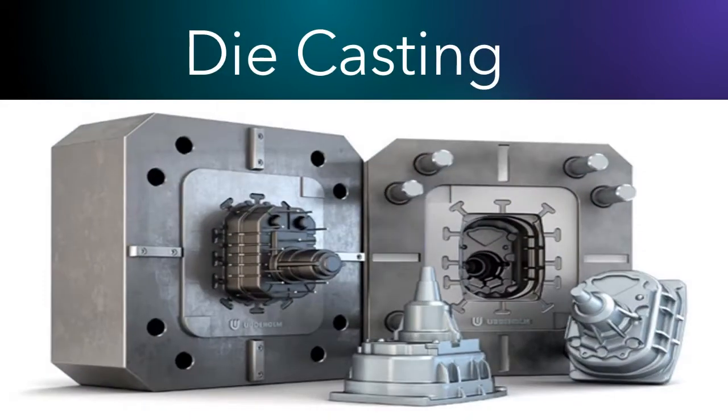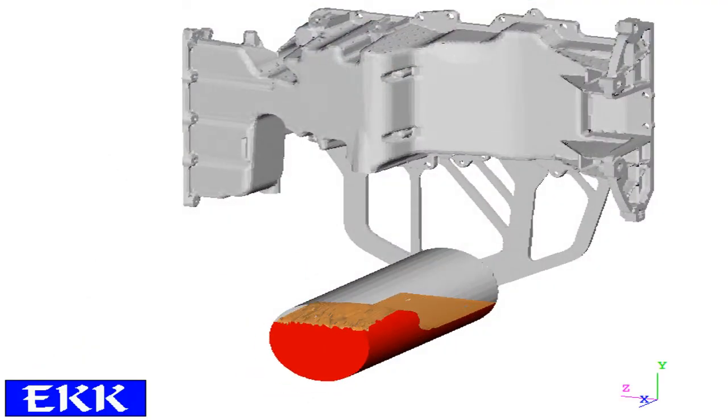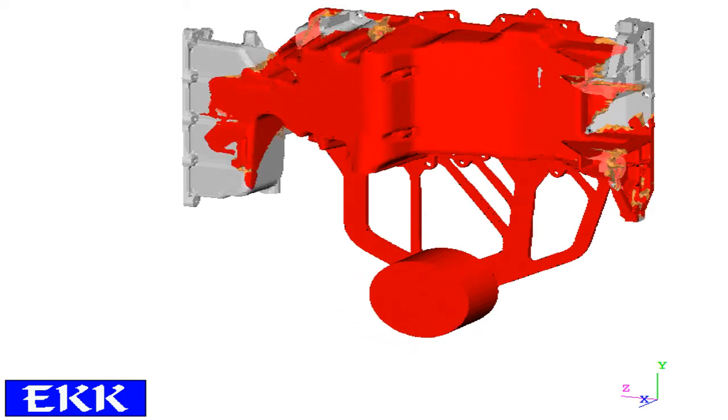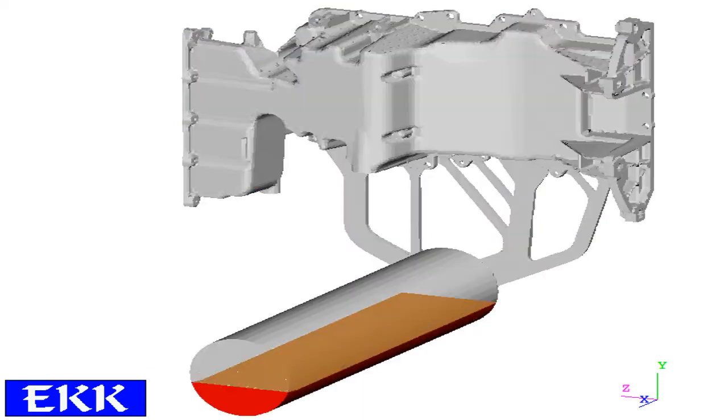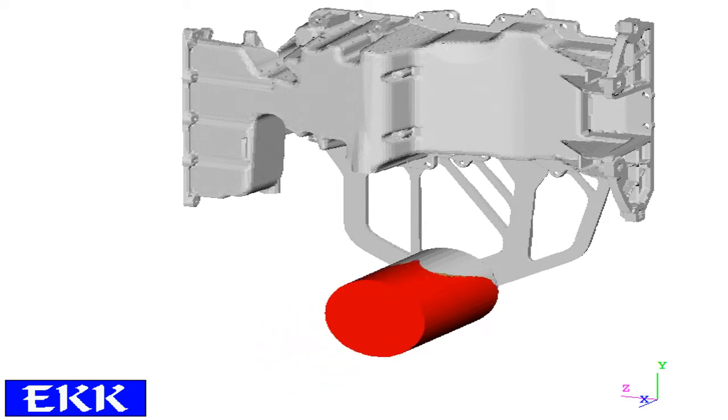Die casting is a permanent mold casting process in which the molten metal is injected into a mold cavity under high pressure. The mold in this casting operation is called the die, and hence the name, die casting. Its use of high pressure to force the metal into a die cavity is what distinguishes this from the other permanent mold processes.